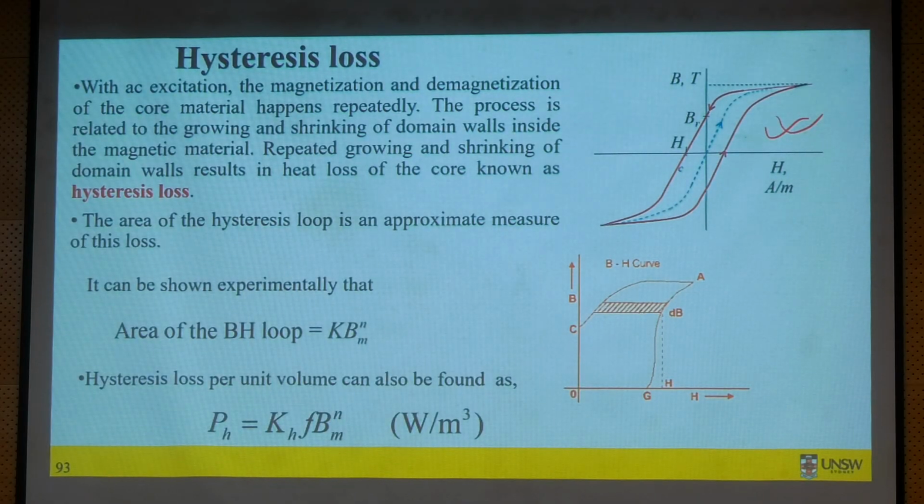Okay? So that's under no load condition. So we can measure under no load condition this iron loss and mechanical loss, and we cannot separate them easily. So for PM machine, if we want to separate iron loss from the mechanical loss, you actually need a dummy rotor. Dummy rotor means you make the rotor exactly the same as your PM machine, PM rotor, but remove the PM, no magnet. Okay? And then run that rotor and do the same no load test, measure the losses, and that loss will be your mechanical loss.